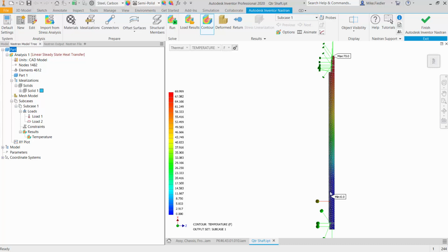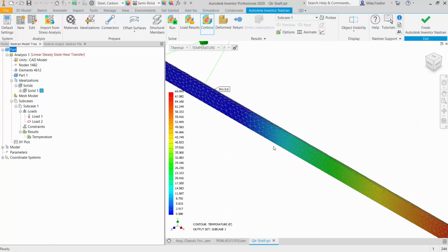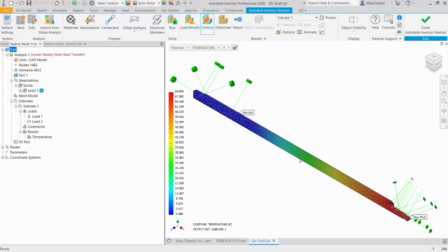And then down towards the end of the model where we have this stuck into some sort of refrigerator or coolant, we're holding those surfaces at 0 degrees, and then of course we have to have some sort of gradient between those, right? So we have temperatures around 30 degrees, 35 of course somewhere in the middle of this geometry. So that is what the thermal analysis does for us, and some of the thermal loads that we can apply to the geometry.